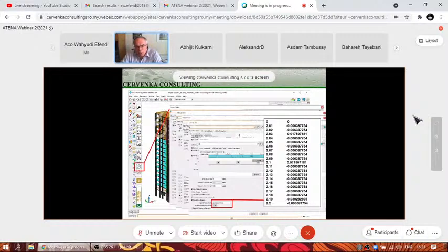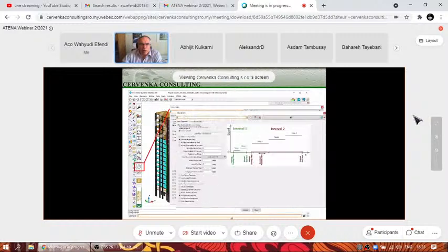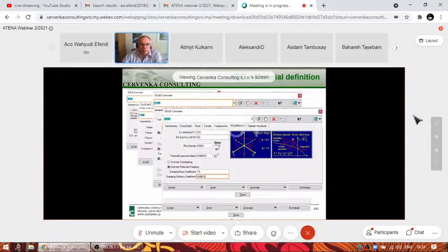Here maybe I should mention that this mass definition of the materials, if I go back to this dialog here, mass definition exists also in static analysis in ATENA, also in creep analysis. And there it is actually not used for anything, except for the eigenvalue analysis. Because even in static analysis, ATENA allows you to perform eigenvalue analysis.